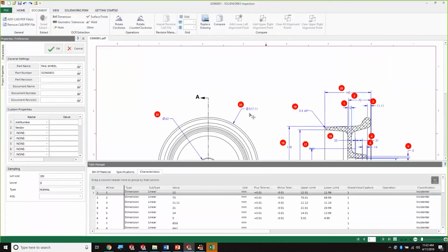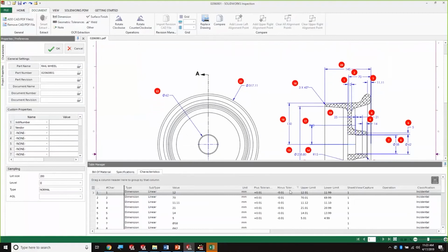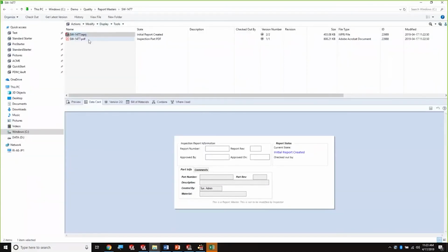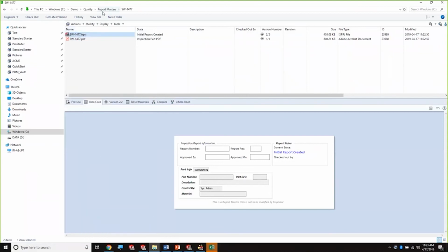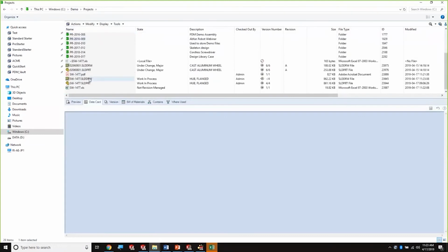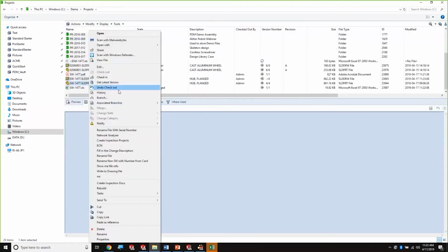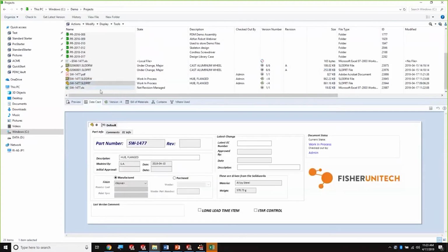Looks kind of like this. This is a different example. This would be for non-CAD people to come in and manipulate some of the information here and spit out the inspection information. All right, so it's creating the link there. What I will do is I'll use the exact same functionality I used for the grease to create a link between the inspection information and the original CAD document. Okay, this only has to be done once. Once I have created a link here, PDM will remember it.